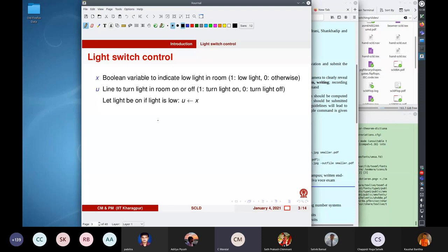We will not go too much into the electronics, but just note that there is a reason for that. One basic reason is that it takes more time for the voltage to change between 0 and 5 than between 0 and some lower voltage, say something like 3.3 volts or even less.